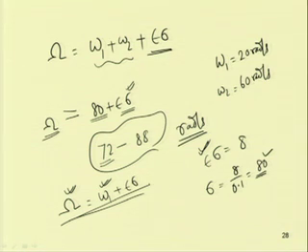So, for example, if omega 1 is nearly equal to 10 radian per second, we can have the secondary oscillation or secondary resonance condition. Also, we may have this capital omega nearly equal to twice omega 1, that is nearly equal to 40 radian per second.